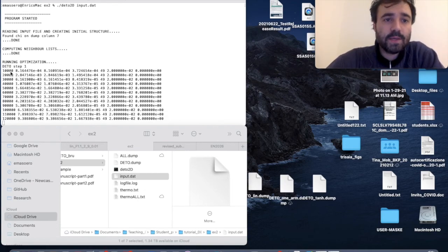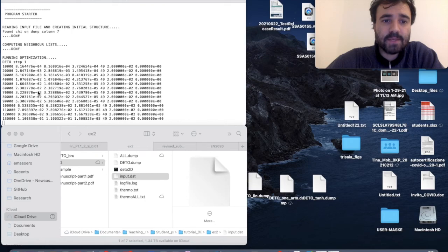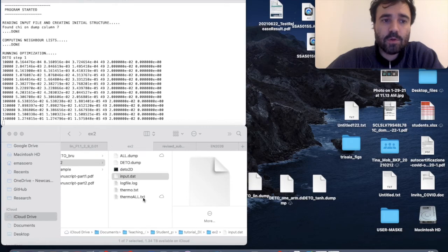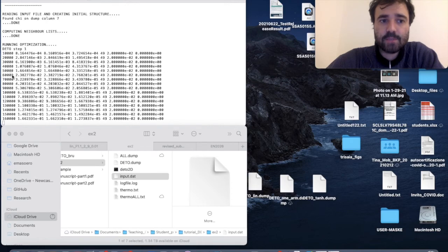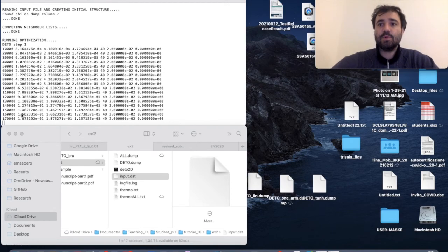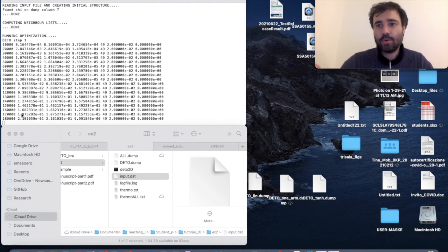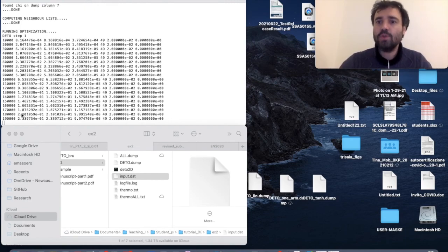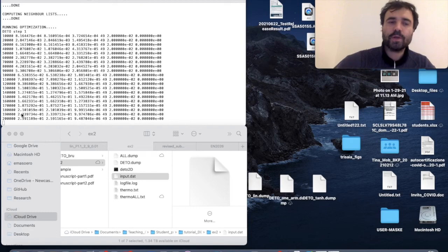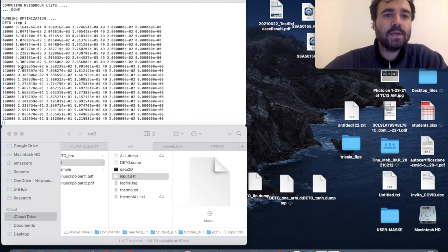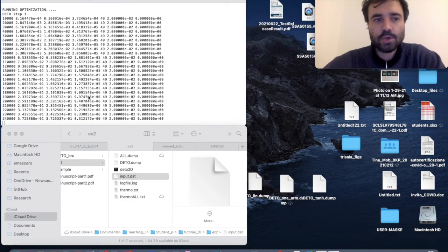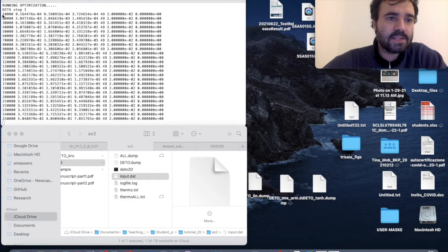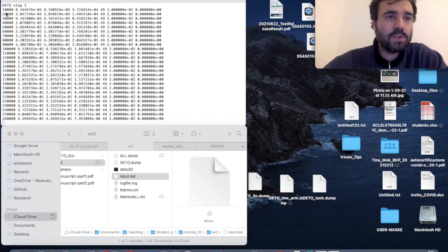And what we care really is about these results that are being recorded now in the thermo file for the first step. So when the first step will be over, then the system will redistribute Xi, but at that point it's starting actual optimization. We don't want to optimize the system, we only want to record force displacement in shear for the final structure from the previous optimization. So we only care about the results on the step 1. So what I will do now, when the step 1 is over, I will plot the results.